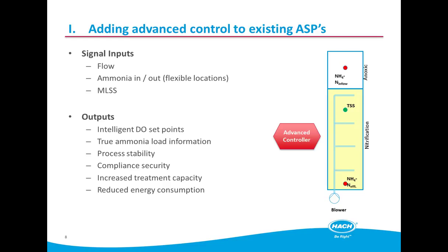However, with the sludge age controller, you ensure the compliance, but in a more efficient way, so probably saving a little bit more energy. Yeah, there's certainly more energy to be saved. Obviously, if you've got a lot more bugs in the system, there's a lot more respiration, so you've got to provide greater levels of oxygen just to maintain whatever DO set point is the correct set point.